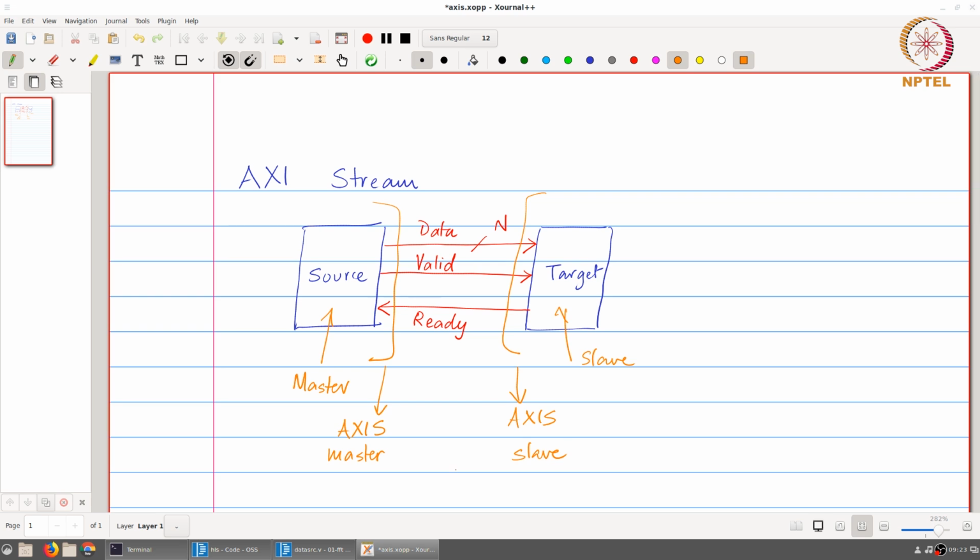Now, for our purposes, we have already generated the input data in a hex format using the DataGen script that was used when we set up the FFT HLS project. We would like to load this same data into some kind of Verilog module that can then act as an Axis master and give out this data.